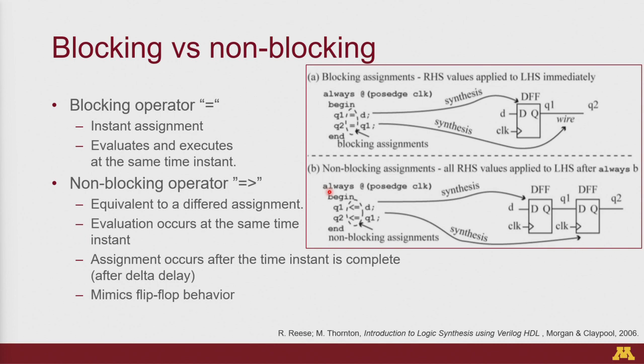The way you think of it is as a kind of continuous assignment statement. What kind of logic uses continuous assignment statements? For example, logic gates. An AND gate will not care what any other system is doing. Whatever input it gets, it will give you the AND of those two inputs and then give you an output.